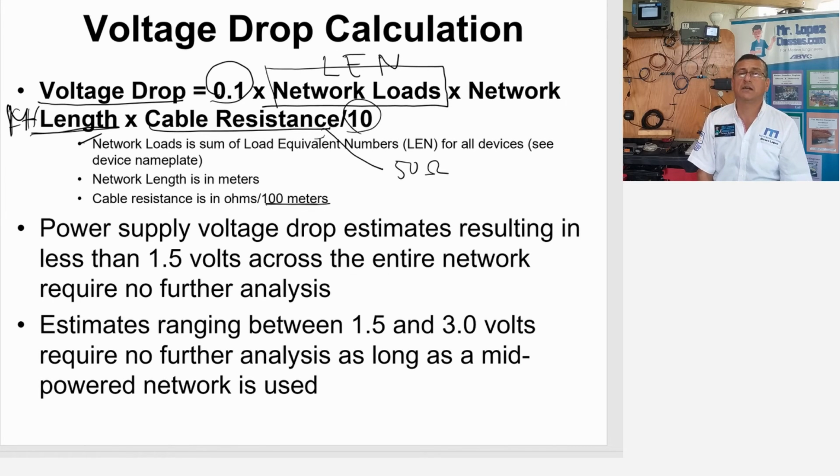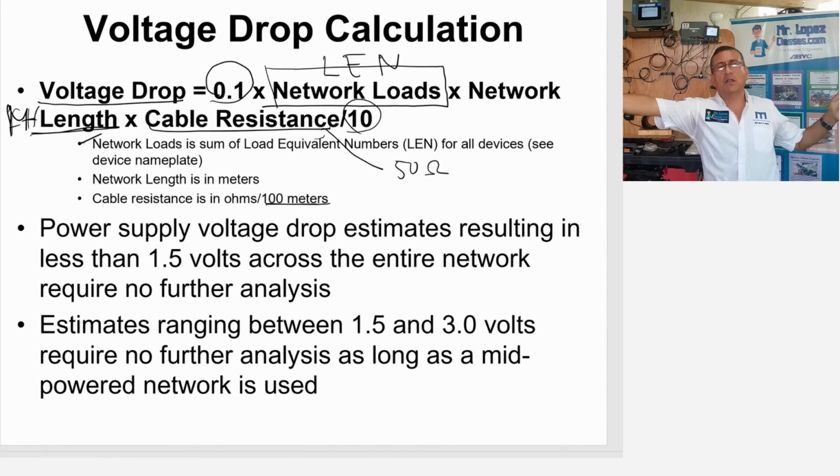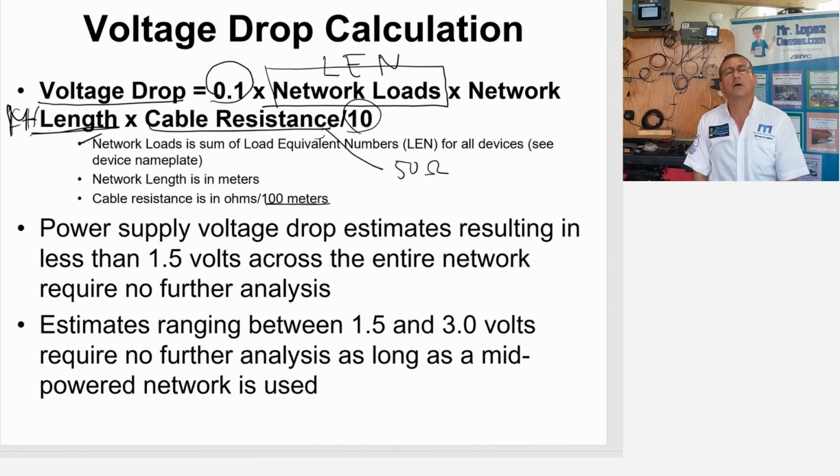Okay, and another possibility is that the voltage coming from the sources of power is not appropriately distributed on the backbone. I have only one source of power at the end of the backbone. And how is the total length? Oh, the total length is 150 meters. Oh yeah, papi, it's too long with only one source of power.